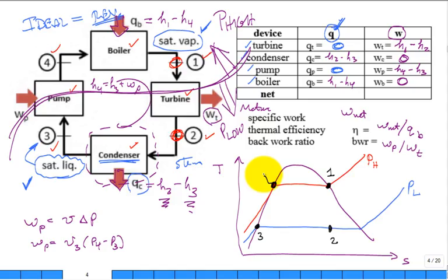No. And last time I even said we exaggerate the spacing difference between the blue and the red line down in this state 3, state 4, and often it's less than 0.5 degree C temperature change between the two. Very small, but we'll exaggerate it on illustrations like this. But those lines are very close together. State 3 and state 4 are almost on top of each other. True?